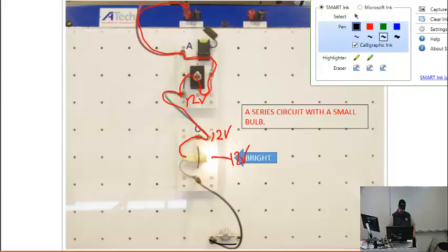So our ground comes up and kind of feeds this, right? Well, when our voltage comes down, we actually will have just enough voltage to go all the way back. And so right here at this tap, we might see, I did that kind of bad, 0.01 volts left over. That's what you're going to see at the end of that. And I know that gets a little bit messy, but that's how our voltage is flowing through that circuit. And that's what's happening during each leg of that circuit.